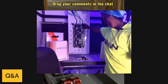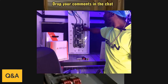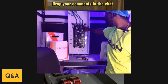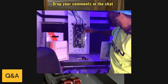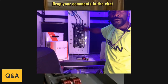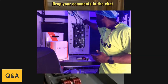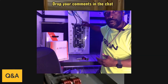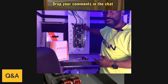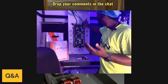This also is, as you can see, this lug here is burnt out. And this lug here, what happens is it's melted. For all those who can see right here, it's a melted lug. Obviously, I cannot use this panel anymore. You can see how I strip my copper wire by code, okay? I cannot have too much of this stripped out, and my two hots will land here.